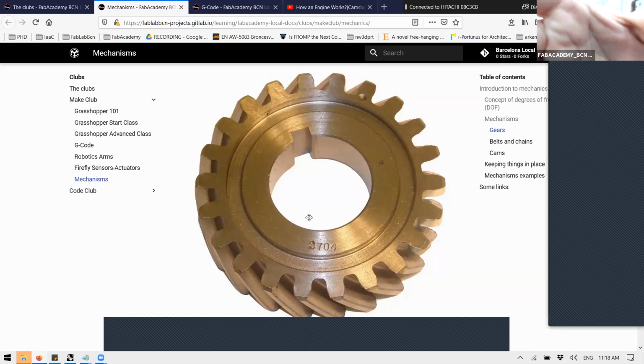Expensive cars also use helical gears, but in rally cars, if you look at the inside videos, it's all the time a whine, because they use straight gears, which are slightly more efficient. They don't care about the noise.